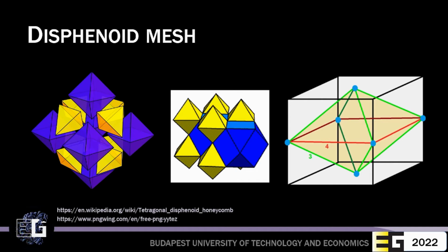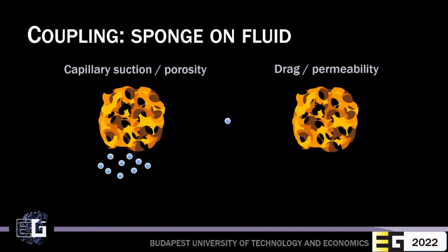Parallel GPU constraint resolution can be executed on all constraints in 24 passes without conflicts. Because of the identical shape of the original undistorted elements, the coefficient matrix for deformation gradient computation is a global constant that applies in every class when adjusted for orientation by swizzling and inverting axes appropriately. This reduces memory requirements and saves significant computation bandwidth.